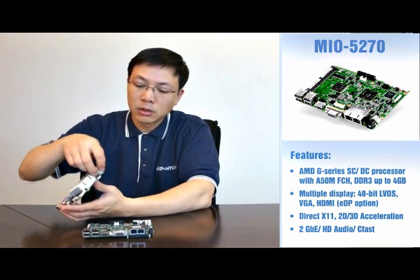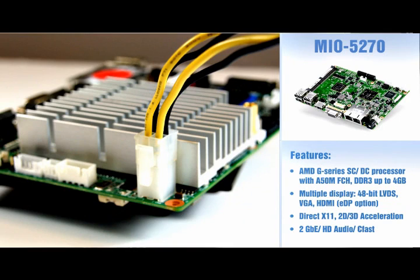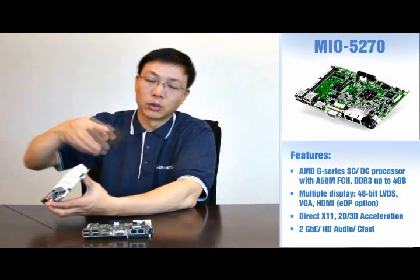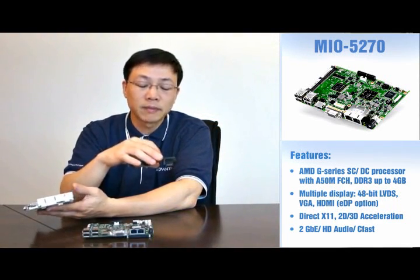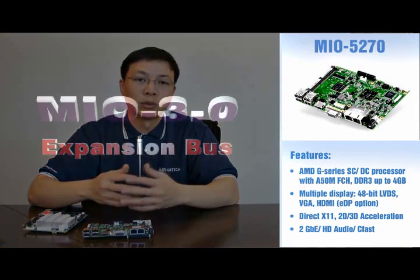Traditionally, with a single board computer, the industrial type power connection could cause interference when you're using a heat spreader plate, because after you add the additional power, when you plug in, the power connector will be taller than the top surface of the heat spreader plate, and in this case, customization will be required, and that will add to the necessary time to market.